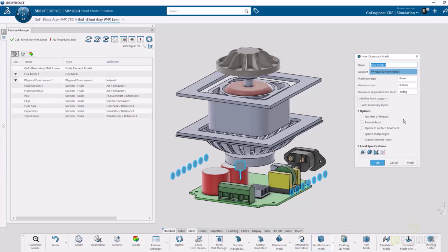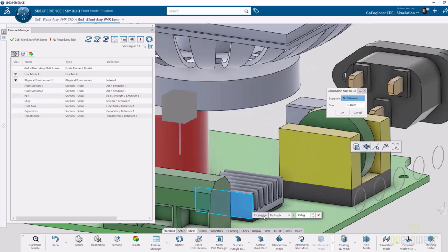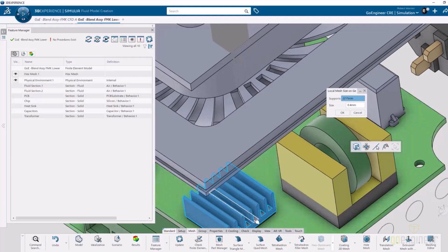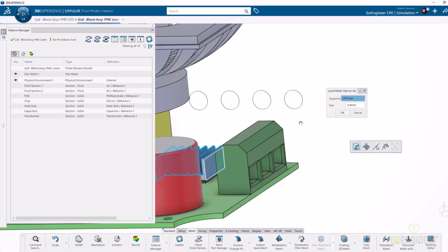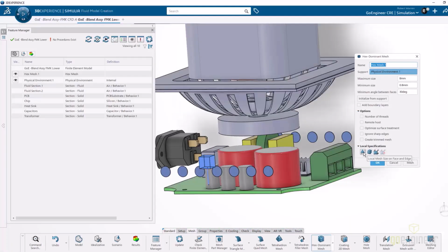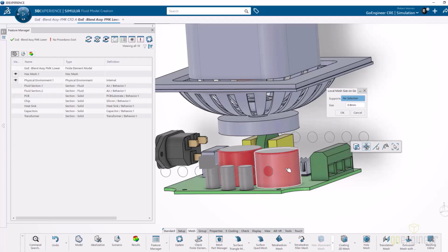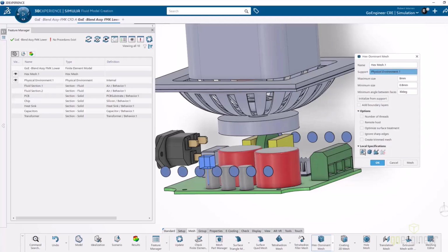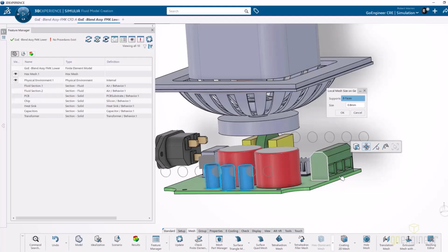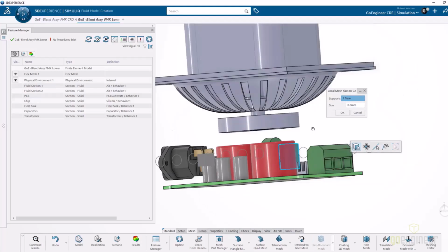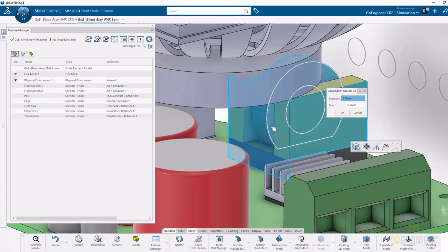So we're going to go ahead and do a mesh review first. So we're going to look at adding some mesh control into the model. Now, there's two meshes because we're doing heat conduction and solids with this. We're going to add mesh control to the fluid domain. So we want to make sure we have good representation of the fluid in and around these solids. And then we're actually going to mesh the solids themselves as well.